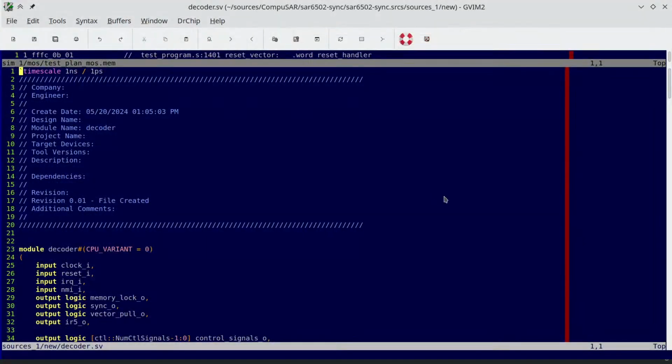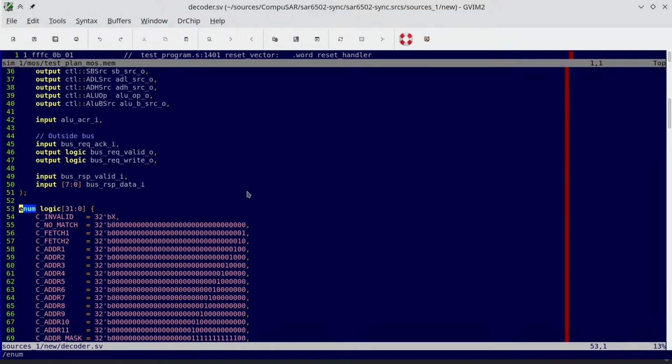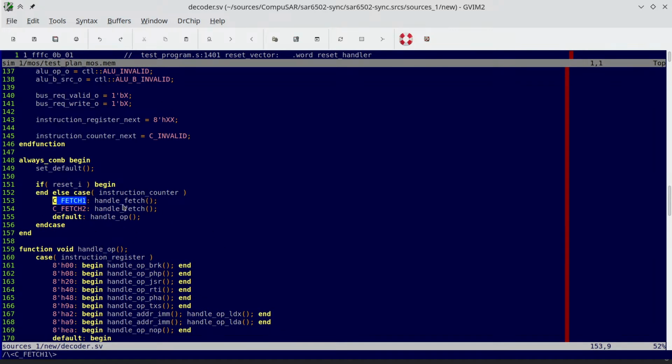The instruction processing itself always begins with two fetch cycles, and they're always implemented the same regardless of which opcode we're currently executing. The fetch cycles use the program counter to fetch the opcode we're executing, and the address immediately afterwards, whether the opcode needs it or not.